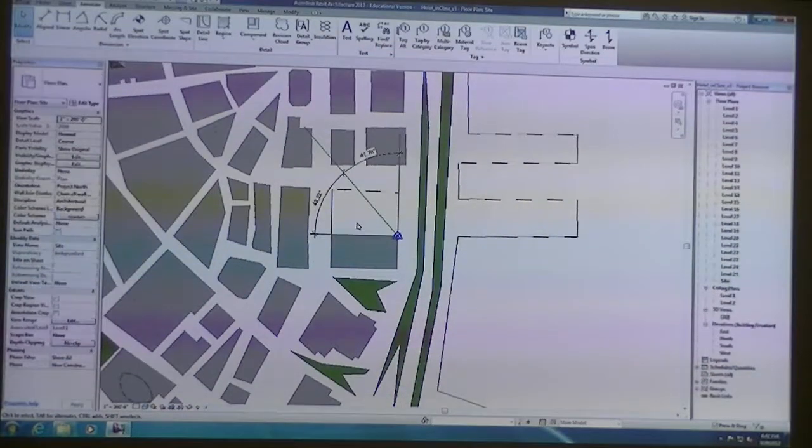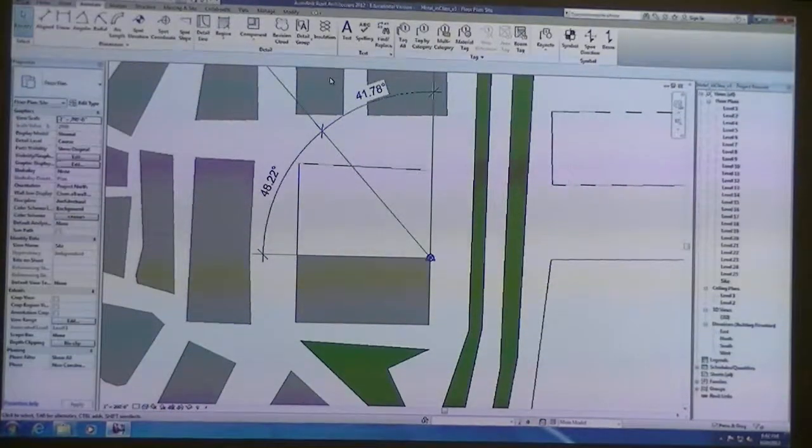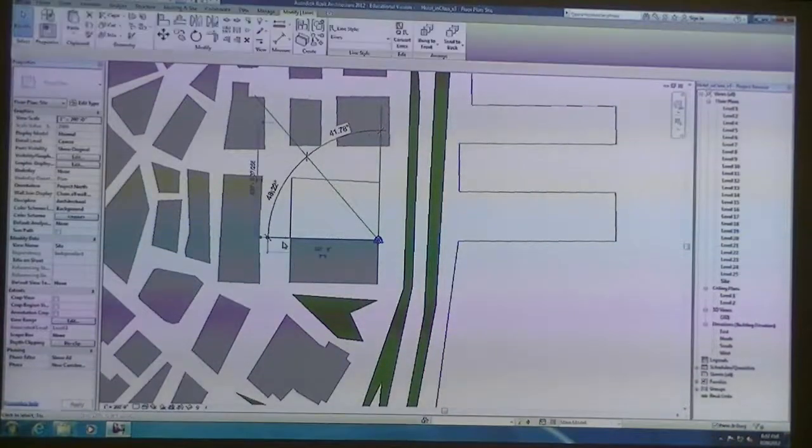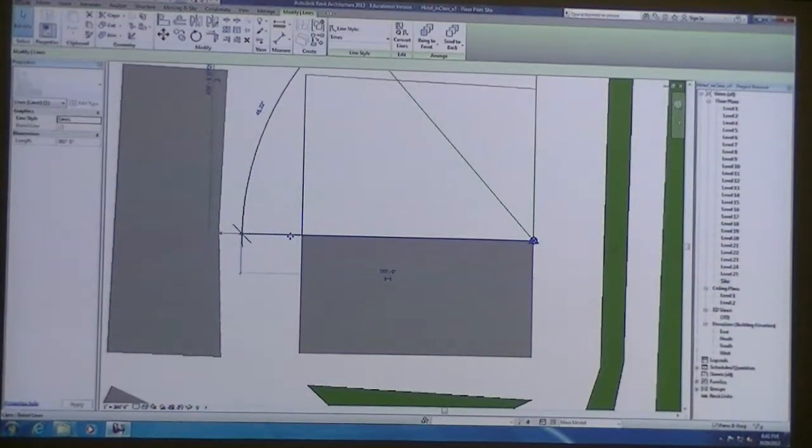How did you edit your angle? Did you just type it in there? No, I rotated it by, when I selected this, I moved my origin point, the center. So you were saying that yours wasn't 48.22. Oh, I redrew it. My line was slightly off axis, so I deleted the horizontal line and drew it horizontal again. But you could also select that horizontal line, and because you have that dimension of 48.22, it'll pop up blue, and you could actually edit that dimension at that location.